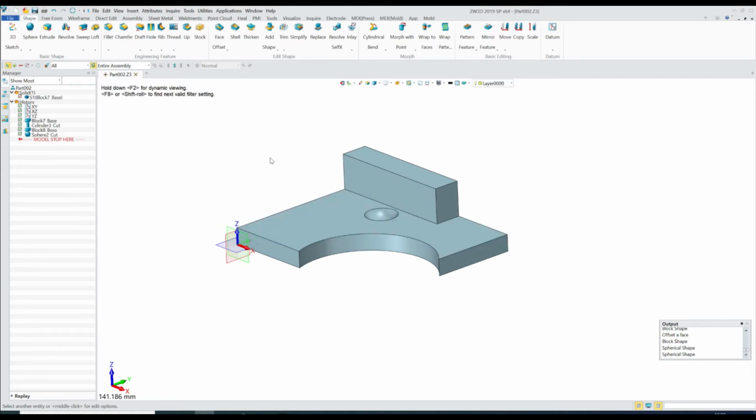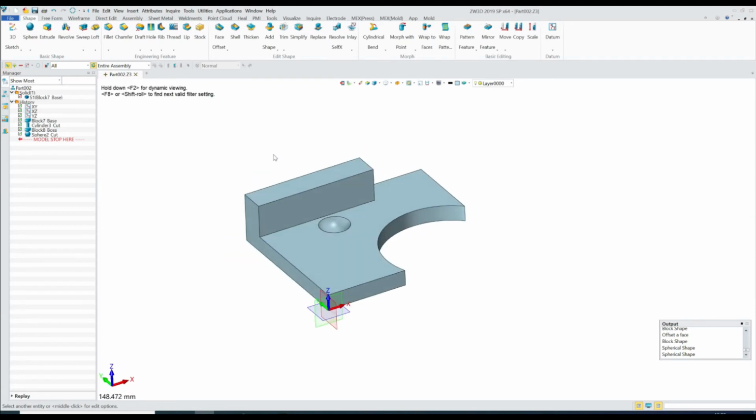But if you want to design something more advanced that can be modified and changed easily, not only by you but by other team members, I suggest that you go with the classical commands over here. That gives you more control over the process. But one good thing to know is that commands like the sphere and ellipsoid are really handy when you try to get a specific curvature or a specific geometry on, let's say, an advanced surface. That lets you position it exactly where you want, and you can use, for example, remove material, or a Boolean shape, or just add this shape to your design. So it's very handy.